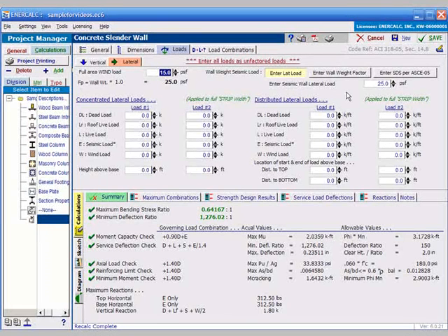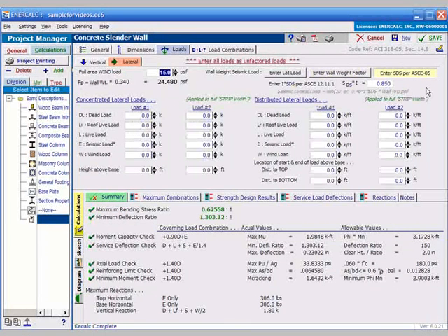We have a wind load that you can apply to the wall, and then of course a seismic load. We give you 3 ways to specify that seismic load, just by entering a per square foot value that the seismic will generate. We allow you to enter a wall weight factor. That 0.25 that you see there will just be applied to the wall weight, and that generates the final lateral seismic force. Or you can enter SDS, I times SDS per the building code here, and it'll be transformed through the equations to generate a lateral load there.